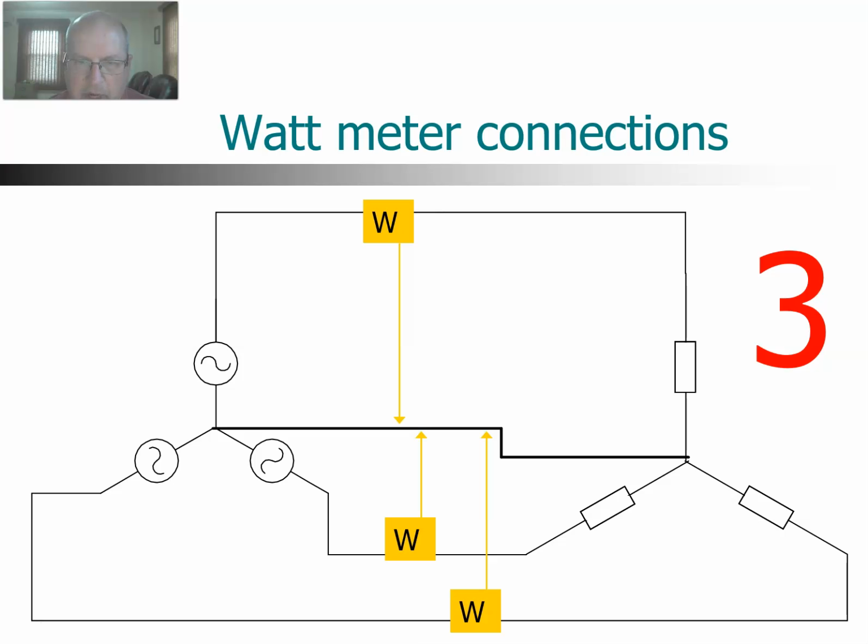So we're going to take 3 wattmeters and we're going to change the wiring just a bit so that we use a different voltage reference point. We're going to tie all 3 meters to the same point, but that point is going to differ from the neutral by some voltage. And I've shown that as a DC voltage. It might be DC, or more likely it's AC. It doesn't really matter. The point is, it's some voltage different than the neutral voltage.